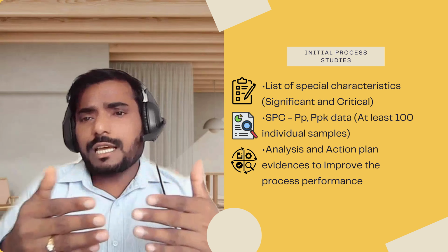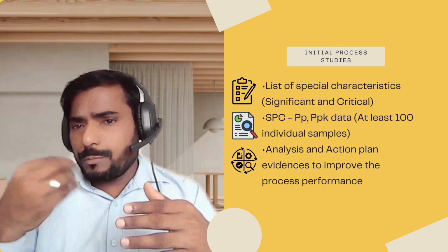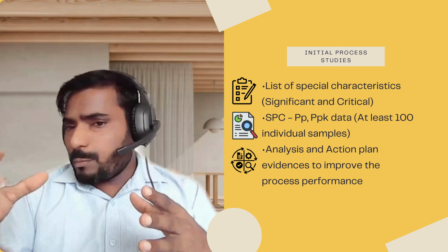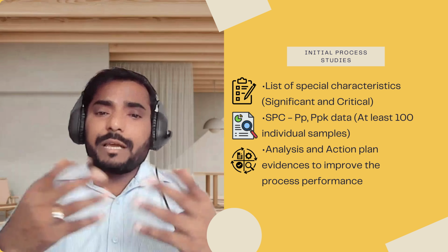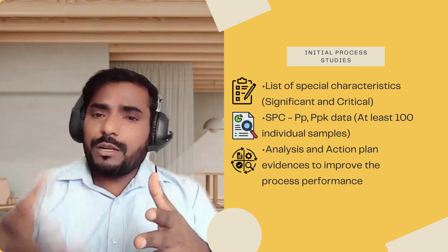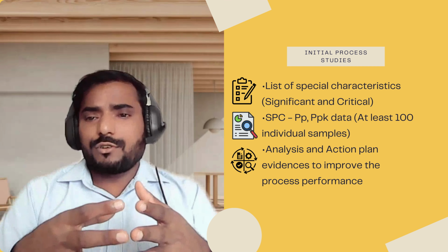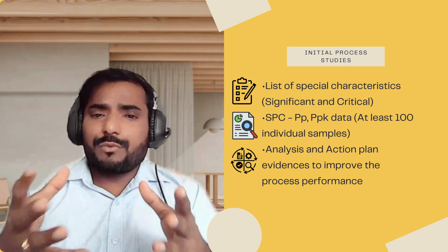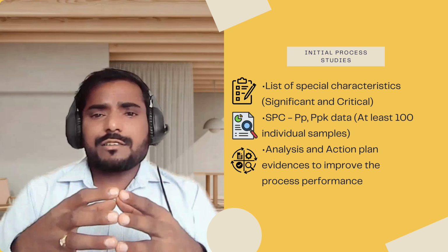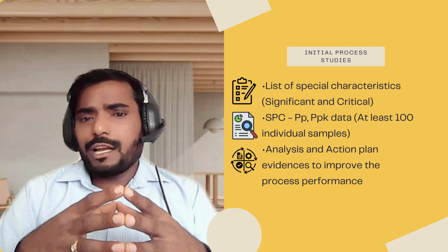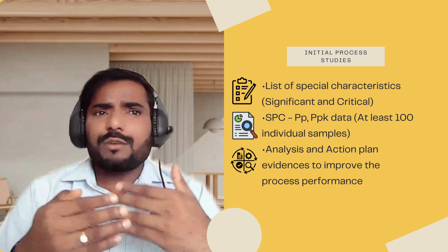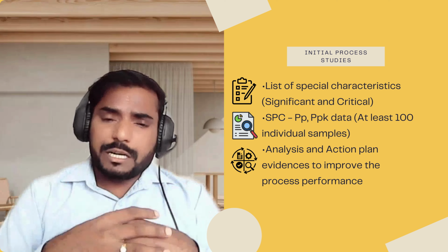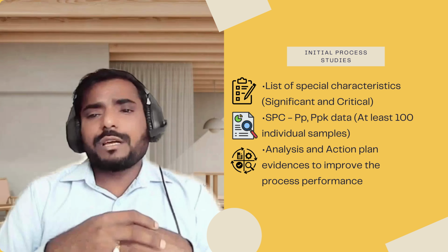If you are going for the on-site visit to give the PPAP approval, then all the components will be produced. You'll be witnessing the whole process, and based on the selected components, you'll be verifying the overall result. So you can verify that. If you are verifying it offline, then get the details and ask them to share the criteria and all, and you can verify the results. And also the analysis and action plan whenever they are not meeting the capability requirements. That one also you should verify as a part of the initial process study.